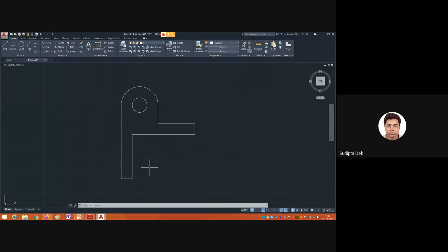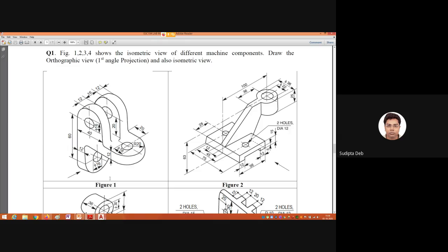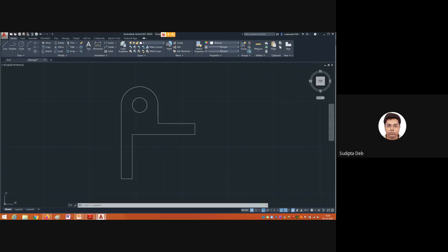Now you can tell me, sir, there was a circle, but the circle is a hollow section, and we are unable to view this hollow section. Of course, we are unable to view the hollow section. So that thing we can specify, because you see in 60, here is the radius. That means this distance is 60. So in 60, we are considering there is a hollow part. So let me draw: O enter, offset, 20 enter, offset.